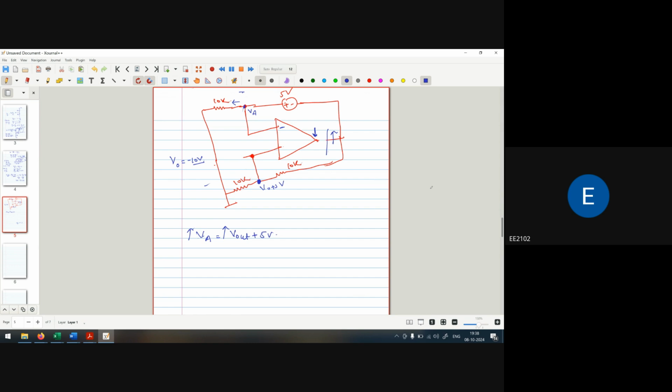So this is my first question: I have to identify whether my supply will be connected at the inverting or non-inverting terminal. So it is the inverting terminal. Sir, but if we take the other case also, the voltage is zero, no? If we are taking this loop, and this is grounded, we can say the voltage at this point is also zero.